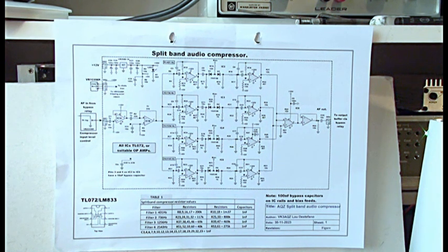However, compression will have occurred if you've gone through a clipper circuit. So the low amplitude 1 kHz components will have been brought up and the high amplitude 1 kHz components will have been brought down. The ratio between what's been changed and what hasn't been changed, of course, is the compression ratio. It can be 2 to 1, 3 to 1, 4 to 1, etc.